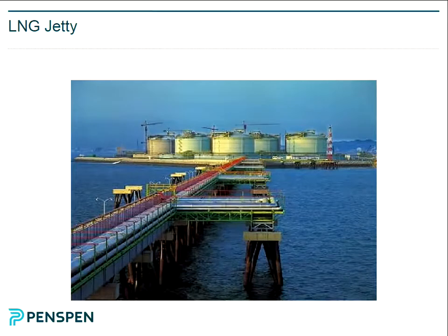But the typical feature of an LNG pipeline is it has a huge amount of insulation, because as that product heats up, it loses gas to the environment, basically. So there's a big cost benefit in having a lot of insulation. Also, if you install this at an ambient temperature, say 10 or 20 degrees, I think this is in Trinidad, I suspect, and then it operates at minus 170 degrees, then you get an incredible contraction and tension forming.